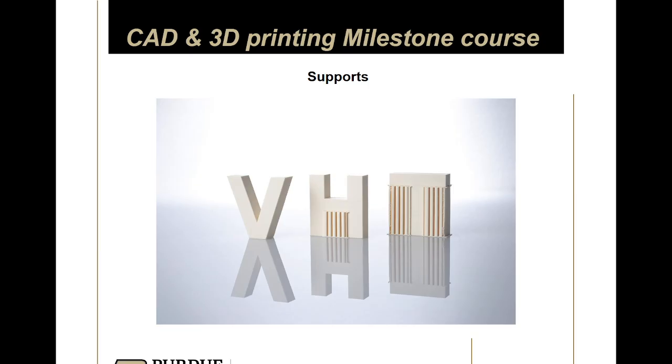Yeah, that's right. Oftentimes if you design something to be printed in a certain way, you can design the need for supports out, right? Obviously, this person printed them straight up, which I don't know why they did, but if they printed it flat, like you said, there would be no overhanging parts, and then you'd be chilling. But in the off chance that you really needed it to be printed in that direction because you wanted it to be strong in a certain direction, supports might be necessary. But again, because you're designing things, you can think about print orientation to see if you can minimize supports.